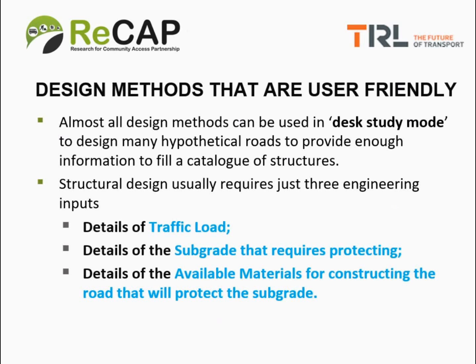So you can vary your subgrade strength, you can vary your traffic level, use the design method and come up with some structures. And then you put those structures all into your design manual, and they become very easy to use. What you need to use them is the traffic load, the subgrade strength for design, and we need to know about the available materials for constructing the road sufficient to protect the subgrade.